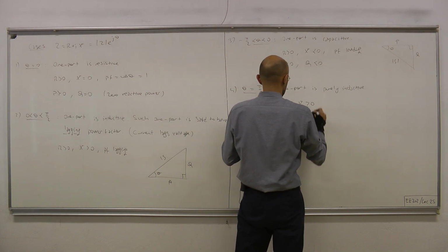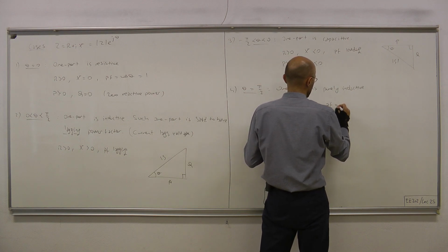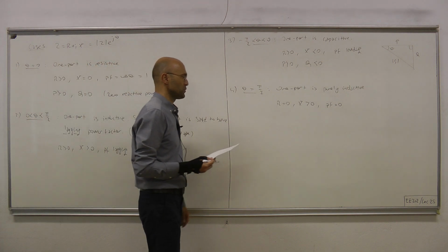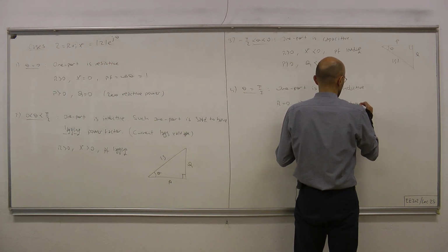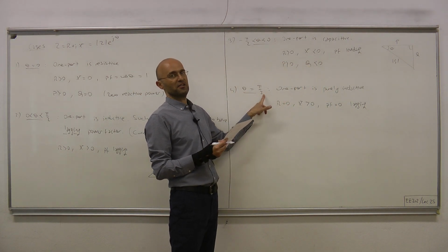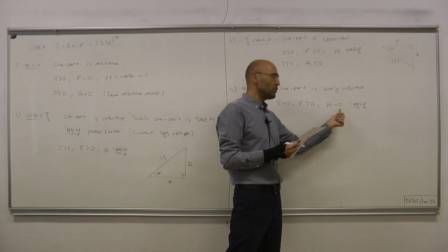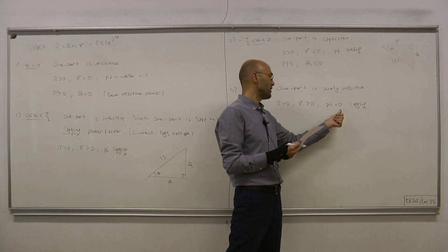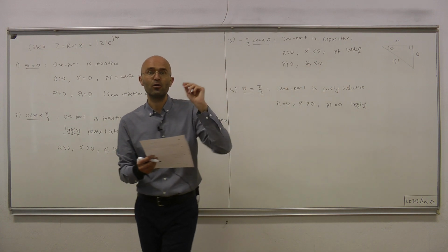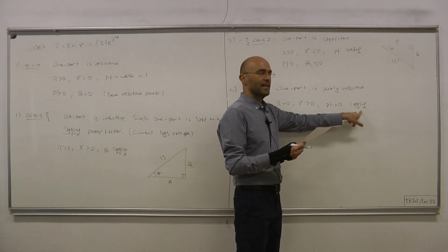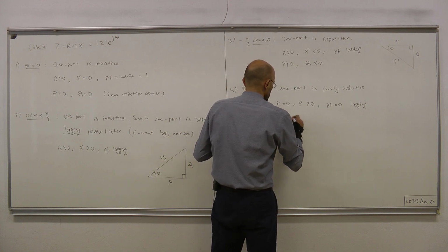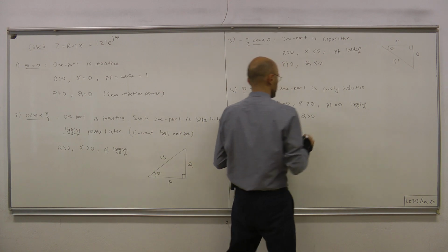The reactance is positive, and the power factor is magnitude-wise as small as possible. PF equals 0. We write here also lagging to indicate that we're at 90 degrees, because cosine of minus 90 also produces 0. So to communicate whether this is plus 90 or minus 90, we put either lagging or leading respectively. P equals 0, and the reactive power is positive.